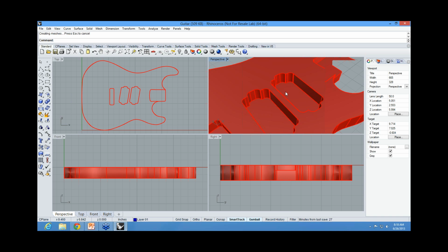the ability to change an existing model. Of course, this is Rhino, so I can explode this into its surfaces, and I can edit those surfaces also, and really give you the ultimate flexibility of being able to interrogate the model, pull the model apart in a way that you can get your machining done any way that you need. That's really the solid editing tools, and I highly recommend exploring those with your own models.